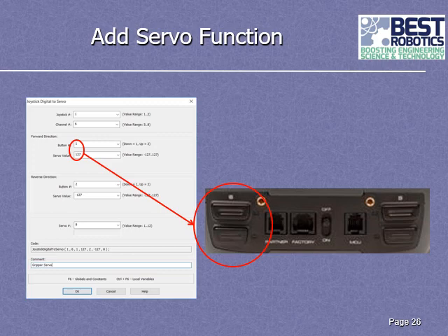So a servo has a center position when it's at rest at the 0 mark, and then you can go plus 127 or minus 127. So in this case, we're going to go plus 127, which says go as far to the right or open as you can go. Now, again, once you put this into place and you decide, I don't know if this is exactly how far I want this thing to open, you can come back in here and you can play with this number until you get it to move exactly how much you want.